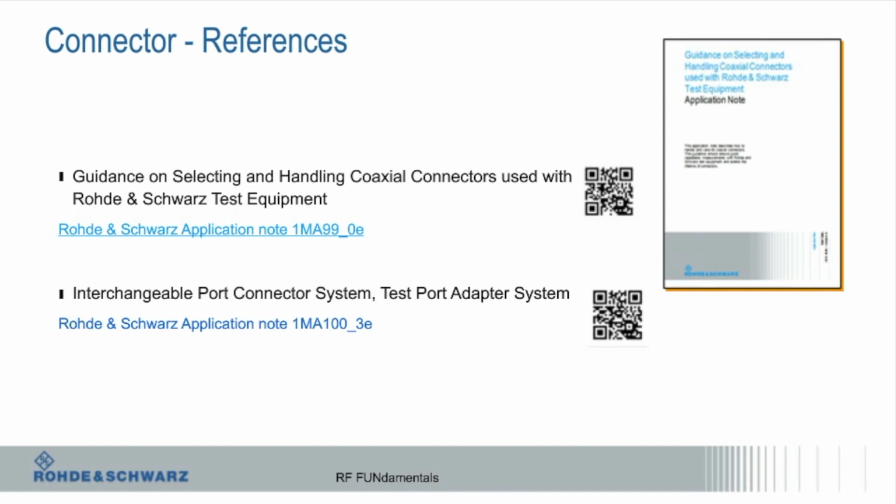Let's see if it shows it in here somewhere. Yeah, here you'll see. This is such a close-up, but you'll see the spacing is closer to the center pin. It's pretty hard to tell, but if you look at them enough times, you will. But telling between a 2.4 and a 1.85, I can't really tell. I can tell a 2.4 and a 3.5 kind of thing. And it's okay to put it on there and try it a little bit. But if it doesn't go, then it's probably wrong. I've done that myself.